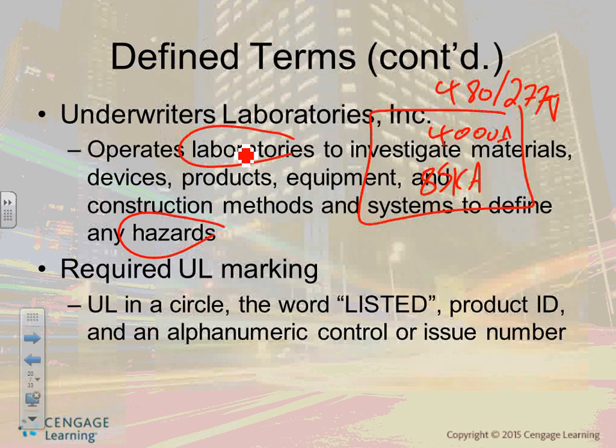And you design it. You send it to UL. Here's the 4,000 amp switchgear, the circuit breaker right there. You want them to test that circuit breaker for the switchgear that can handle 85,000 amps. So they have a machine, they literally inject 85,000 amps into it, and it's supposed to handle it for 30 cycles.